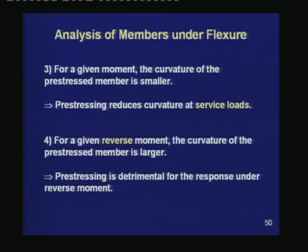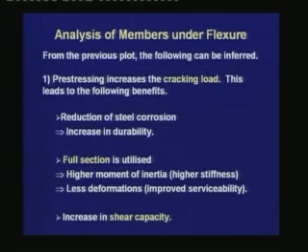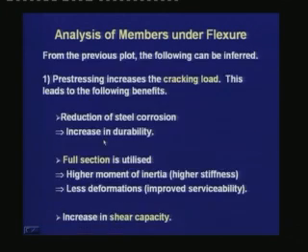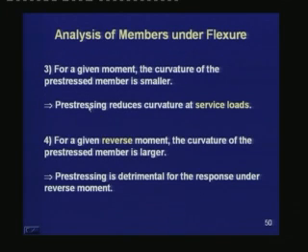The third observation is, for a given moment the curvature of the prestressed member is smaller. If we go back to this curve and if we look at the two values of the curvature at a particular value of the moment, we see that the curvature in the prestressed concrete member is less than the curvature of the reinforced concrete member. Hence, prestressing reduces curvature at service loads, which gives less deflection at service loads.